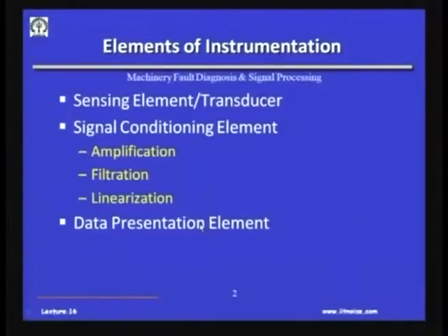And the next element of this instrumentation, the last element, very important, is the data presentation element. Okay. Because finally, you can call it data presentation or data further analysis, once the signal has come from the transducers through the signal conditioning element to the data presentation element, we have to now see the format in which the data has to be presented.